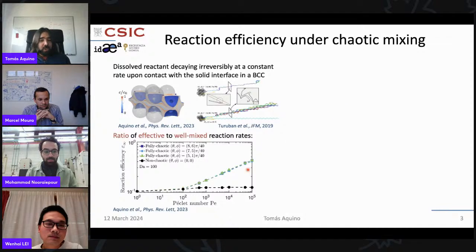Right, so here I'm showing you some numerical results for this quantity at a high Damköhler number of 100 in this case. So when you look at a low Damköhler number, which means slow reaction compared to diffusion, you basically don't get any effect of the mixing dynamics of the transport, because just diffusion on its own is enough to maintain the pore space mixed.